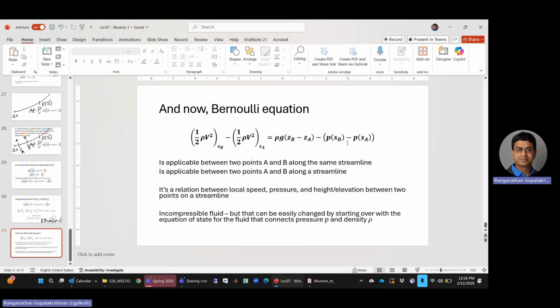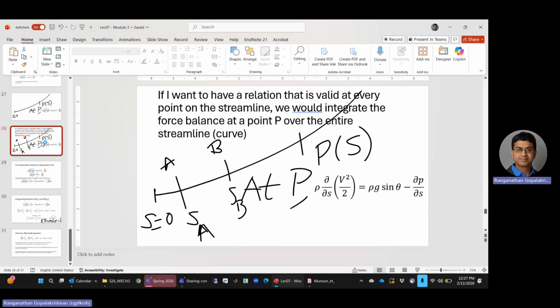So in section 3.2, Dr. Hochstein, who is one of the authors of this book, says this is the celebrated Bernoulli equation. That's his word, the celebrated Bernoulli equation. Sometimes it is also written as, now 1 minute, then I'll let you write. I just said that I'm picking 2 points, A and B, right? I didn't place any constraint on which 2 points. We can apply this Bernoulli equation between any 2 points as long as they are on the streamline.